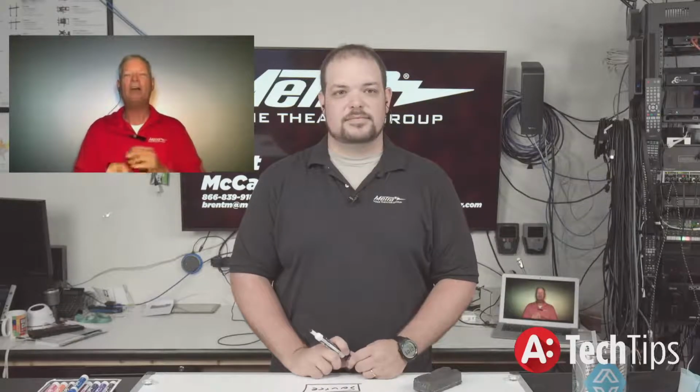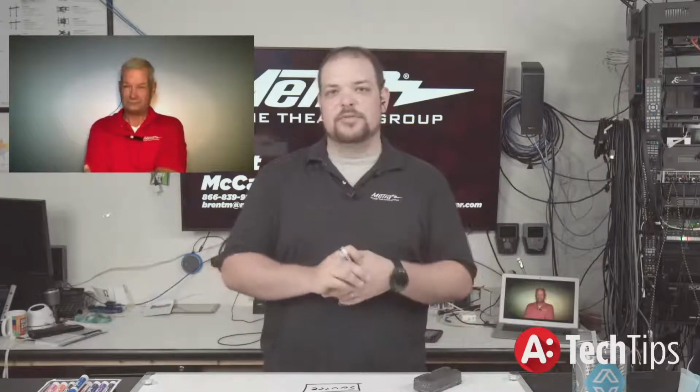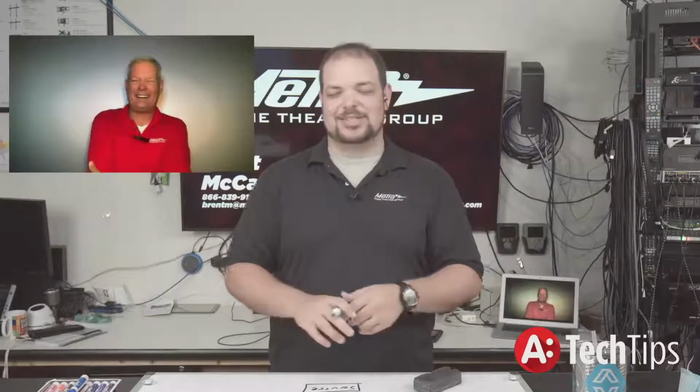Now, when you look at ours, you've got a full 18 gig capability. That means it will support anything within the HDMI 2.0 specification except eARC. And I don't know of any that does yet. A lot of that is because of how you route that and how you send it back to wherever it needs to go. It's very difficult to have all that matrixed as well as the video matrix. There's just a lot going on, so it's a lot to ask for today. As we move forward into the future, we may see those start to come out. Personally, I'd really want to see eARC and ARC become a much more stable platform before we see any of that happening on a matrix.